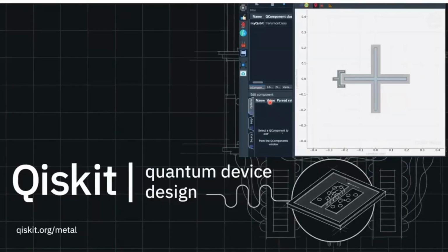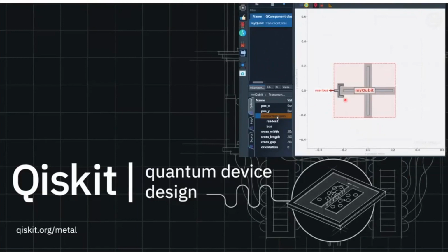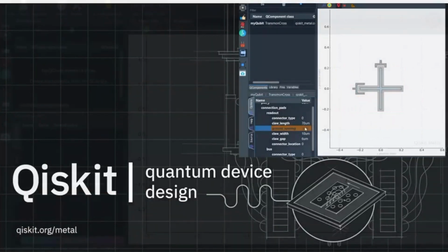Now, you can do that not only with that transmon, you can do it with different kinds of geometries, and you can define your own, such as this xmon qubit here, and there's a particular coupling. You can add a second coupler and so forth. This is just to give you an idea of how that looks. And all of these look a bit like P cells, in that they're parametrized cells, in that you can change all the properties, but they also have a number of other features that allow for simulation, which we'll get to in a minute.